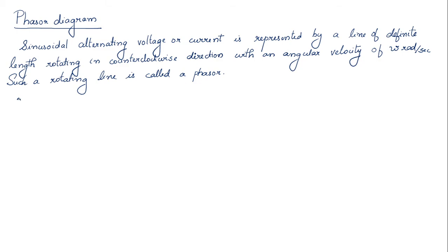I'll show you how we can represent a phasor diagram. Just drawing a phasor, first take an AC quantity here. I have just taken a voltage quantity, that means voltage V is equal to, because the angle is 0, or it is starting from the 0 point, we can say the equation for this one is Vm sine omega t. And this is omega t. Now we are going to draw the phasor diagram for this.